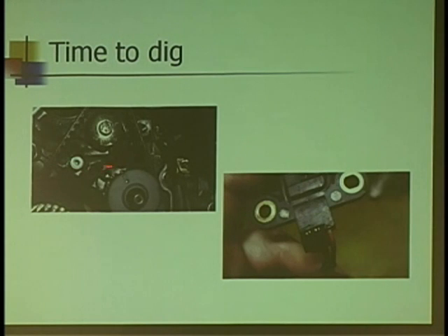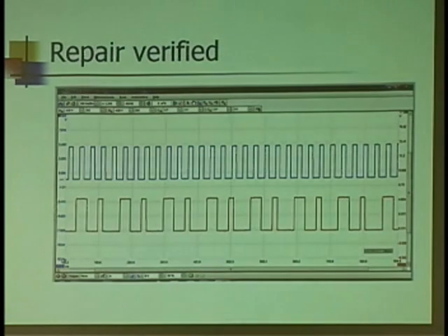And there it's hiding. I mean, you gotta get the belt off just to throw out the harness, and someone was telling me last night this is very common when the timing belt's replaced by someone who doesn't know what they're doing. So, put it back in, get a nice good waveform to use as a reference later on. But now I can also check the electrical integrity of the circuit, right? If I look at this ground point and I zoom in on that, would it be the same as doing a ground side voltage drop check?